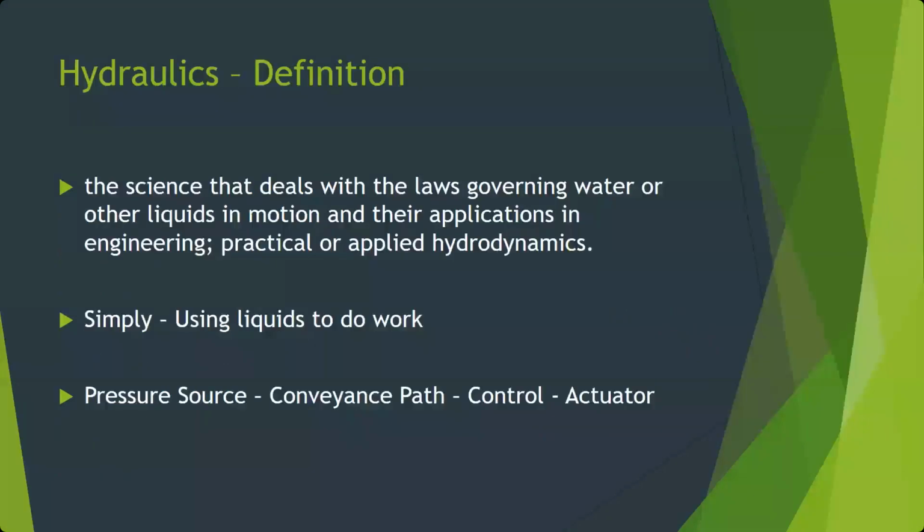And the simple breakdown, if you look at this bottom line here, what is a hydraulic system at its highest level? Most simply, you have to have some kind of a pressure source, something that's making the pressure, and we're going to be converting some other kind of energy into pressure. Then that pressure is going to be conveyed, and we have to control the pressure, and ultimately it's going to make something move, actuate, or activate.